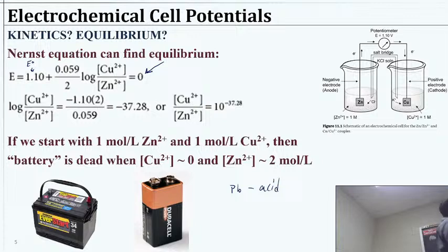Actually, it's probably not directly related to that, but the other thing that can happen is your leads can get corroded. Now that one's a little easier fix, right? You scrape off the corrosion on the surface, it's kind of rust and whatever else. And these leads, I think they are probably also still lead, so you want to make sure you wash your hands if you do that.